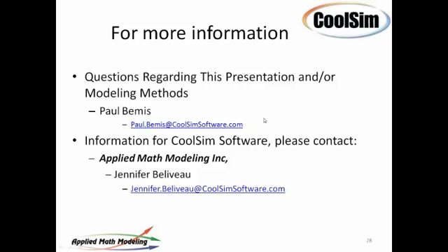And then this is just kind of a follow-on, that the strategy being put forward in the webinar is based on 20 degrees Fahrenheit delta T. And the comment was that's not what currently made servers produce, except when incoming air is too high. And then, of course, leading back to should the strategy change with typical delta T? No, the strategy is exactly the same. It's just I was being conservative.